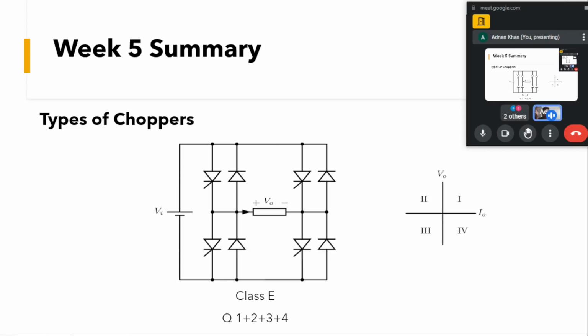Here for this control device we can have a MOSFET or an IGBT. A MOSFET has an inbuilt anti-parallel diode, which is able to conduct this negative current. Similarly, when this and this are conducting, we'll be able to have this negative current flow.